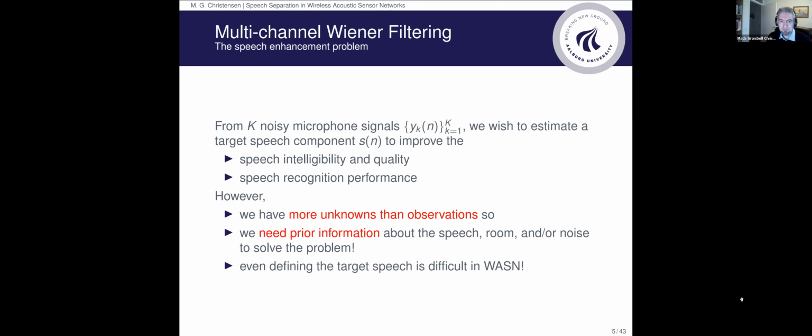So what is the problem at hand here? From K noisy microphone signals, Y_k, we wish to estimate a target speech component S_n to improve speech intelligibility or quality, or increase speech recognition performance. What's difficult about this problem? From a mathematical point of view, you have more unknowns than observations. The only way to actually solve this kind of problem is injecting additional prior information into the problem. That could be about the speech, the room or the noise, so you can actually solve it.